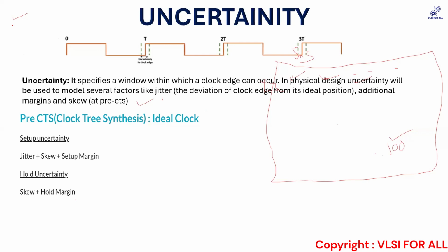You guys are aware, right? Jitter is always between the edges, which are two different edges we are going to take. But since in hold we are doing it on the same clock edge, correct? That's why there is no concept of jitter in your hold values. Now I stated that once your CTS is built, you will have buffers and inverters in your network, correct?